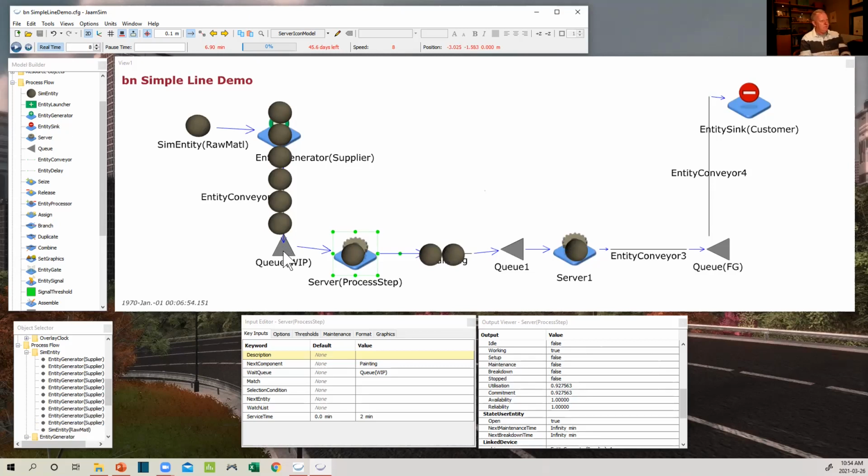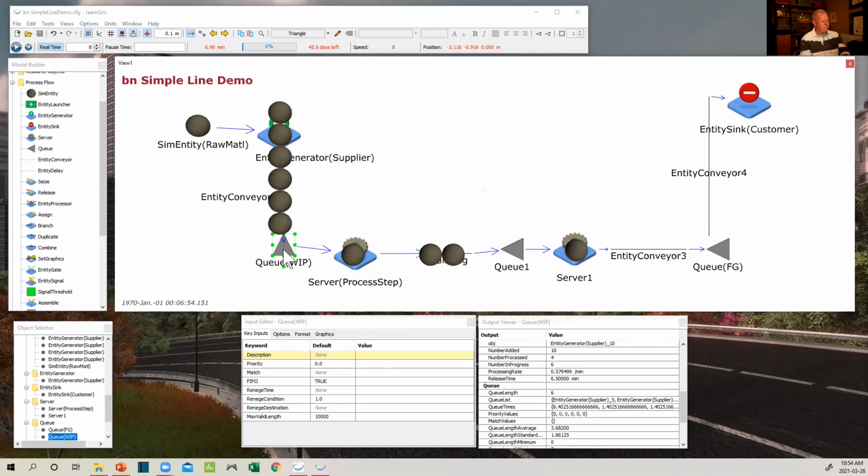So this is where I'll answer your question. If I click on this queue, because this is ugly, and this is kind of what you're saying, you end up with this huge tower. That's the default for these queues, is that everything just stacks up. So if I go to, let's see, where is it? Format. So right now the maximum per line is infinity, and the maximum number of rows is infinity. So I would like to set this for my model anyways, because I'm dealing in things in 5s. So I'm going to set it up so that it'll have 5 per line.